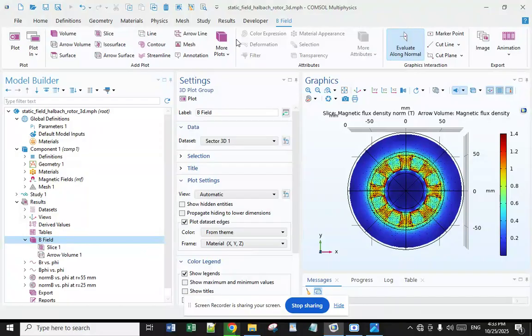With the AC coils also contained within the bore, such self-shielding motor or alternator designs are more efficient and produce higher torque or output than conventional motor or alternator designs. The next one is magnetic coupling devices, which transmit torque through magnetically transparent barriers. That is, the barrier is non-magnetic, or is magnetic but not affected by an applied magnetic field.